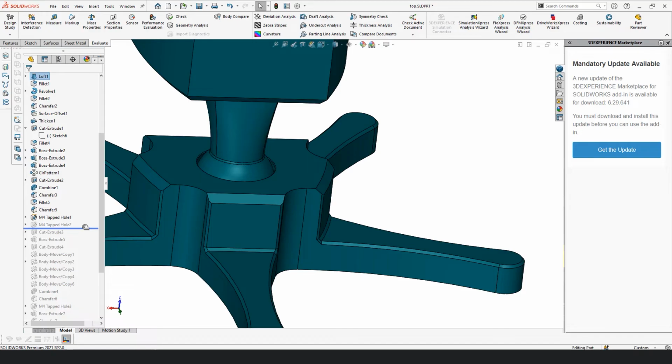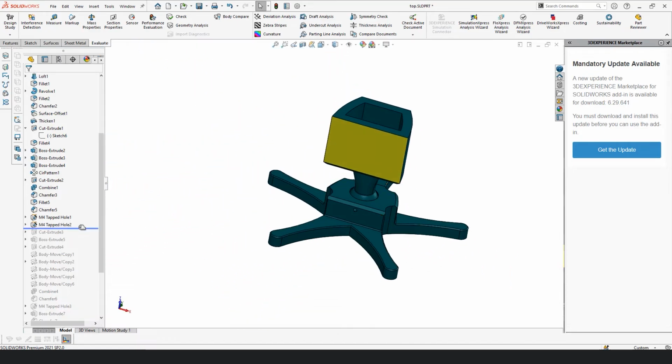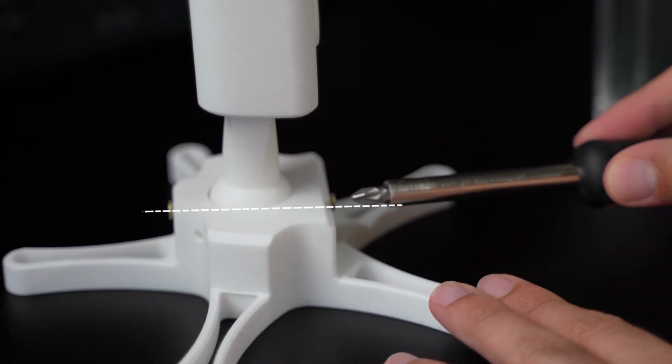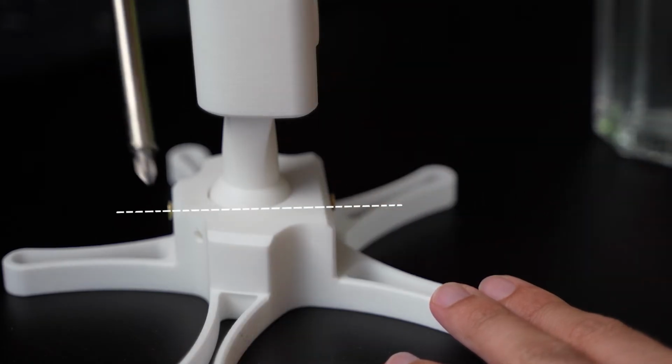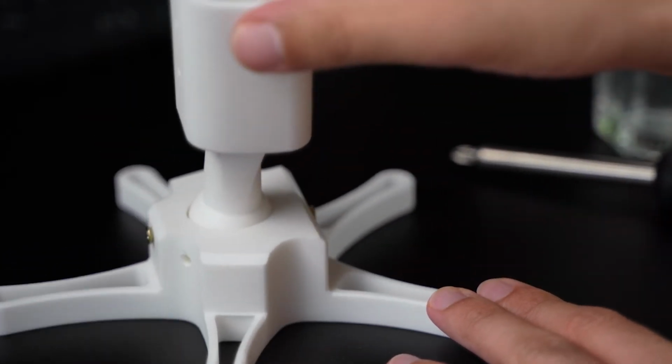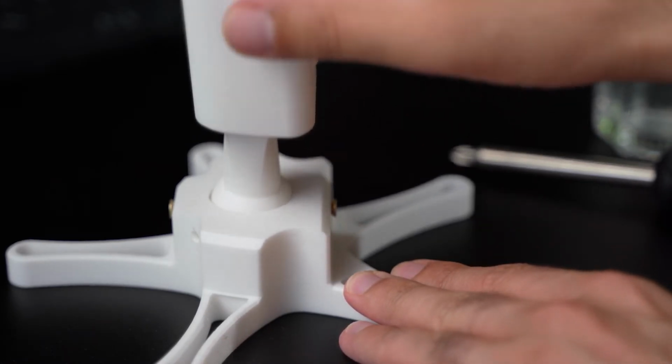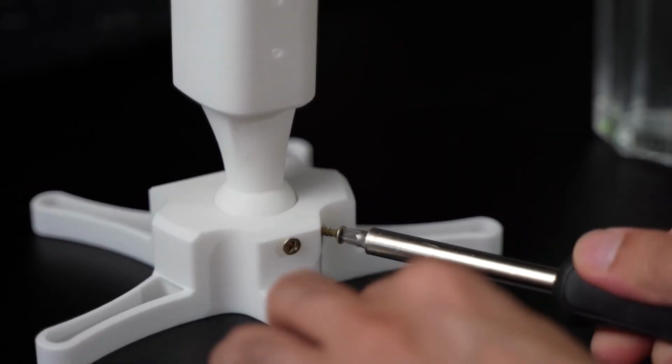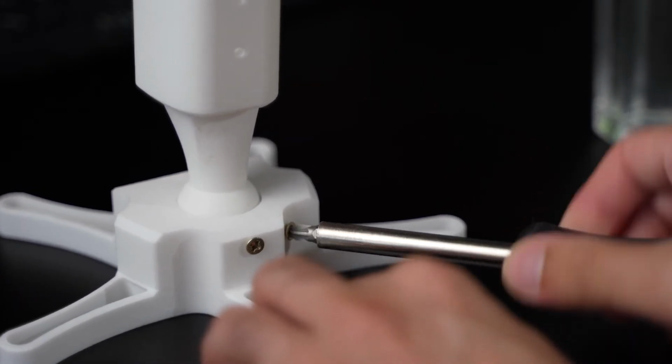Although, as I said in the previous video, my mistake was that I only took 2 holes into account, and the holes lined up and created some sort of an axis, which left the ball with 1 degree of freedom. We don't want to leave it with any degree of freedom. When it's fixed, it's supposed to be super fixed. So I had to drill a 3rd hole and insert a 3rd screw to make it super tight, which worked. But I just wanted to walk you through my thought process, how I start from scratch and go all the way.